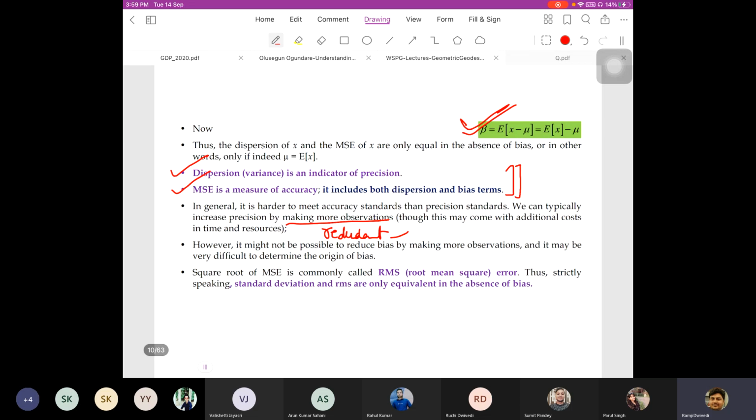But at that time you do not have too much in your hand. The moment your station is established, you have committed thousands of rupees to reach the field. So to be more precise, just like we have done in our deformation monitoring surveys in Uttarakhand, we try to repeat the observations. Suppose we have taken GPS measurements on day 1. Before coming back to our campus, we generally repeat those measurements, just to make sure that whatever happened on day 1 could not be a problem for data processing.